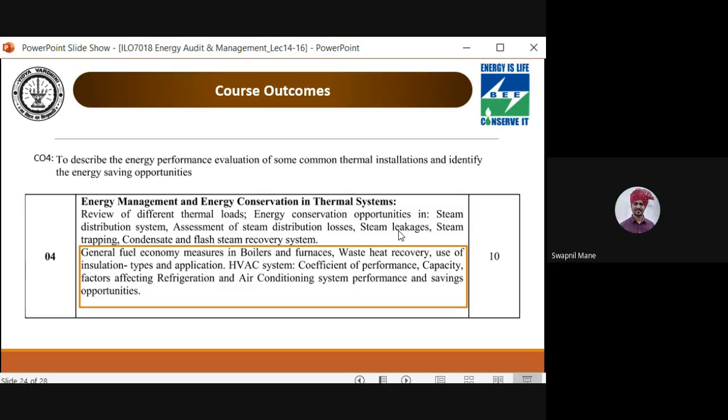In your previous semesters, you must have come across the term boilers. A boiler is an enclosed vessel that provides a means for combustion heat to be transferred into water to become steam. So it is a device which converts water into steam, but not all equipment which converts water to steam can be considered a boiler, because there are specifications required. A steam generation unit will be called a boiler if it is certified by Indian Boiler Regulations.